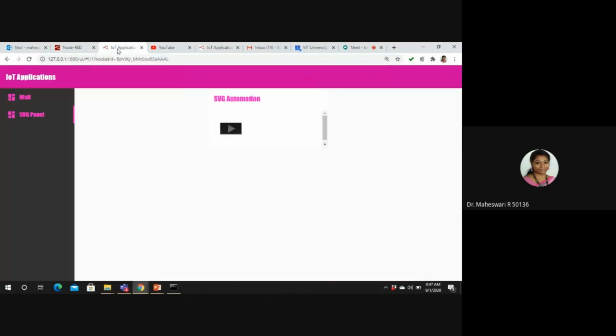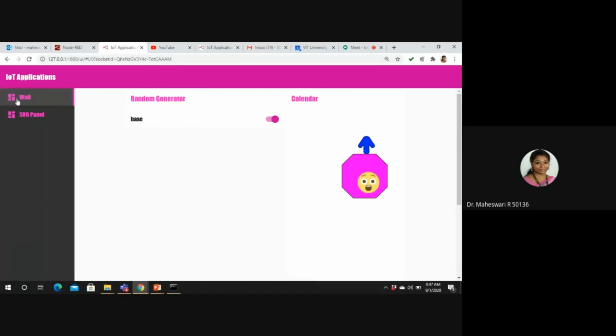So now go to your UI. Once you go to your UI, you could see previously it was here, and now it has moved to this place and it starts rotating. Can you see it's rotating over there? Since I gave a zero-based orientation for rotation, it went to the zero location and started rotating. So you change your parameters appropriately to animate your results.